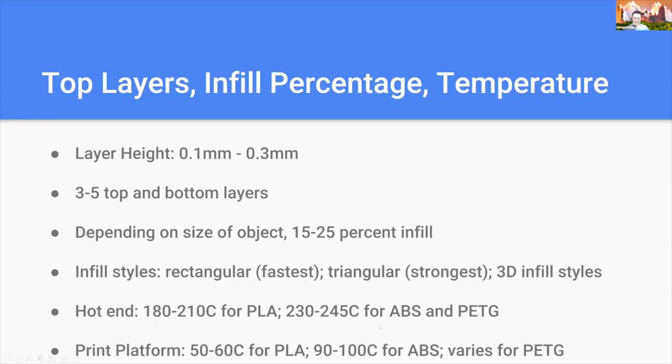And the reason that we heat up the print bed is to prevent the print on the bottom from cooling too much and then shrinking, right? So what happens is that when the print is deposited onto the print bed, if the print bed is only 20 degrees, the print is going to shrink very quickly and is going to detach from the bed from that shrinkage, right? It's going to decrease in size and it's going to detach from the bed. By heating the platform up to 50 to 100 degrees, it allows the print to shrink on a slower basis, and that'll make sure that number one, your print stays on the bed, and number two, there is more uniform shrinkage when the print is complete.